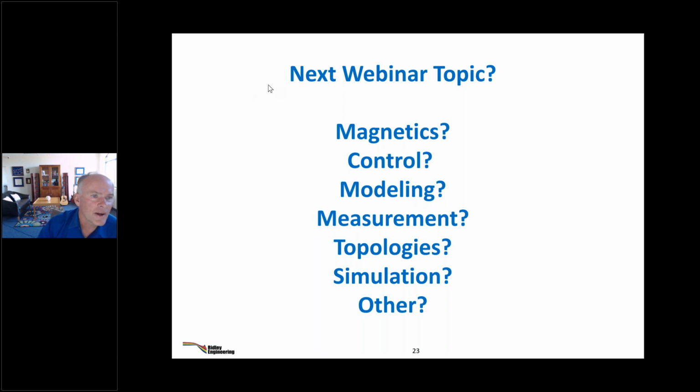Capacitor advice for the high secondary peak currents. People are using multi-layer ceramics in conjunction with organic electrolytics. If you look at this design here, here are the electrolytics, and then down on the board you see some multi-layer ceramics. So it's a combination of caps, as in any high ripple application. Everybody's got a different solution to that.